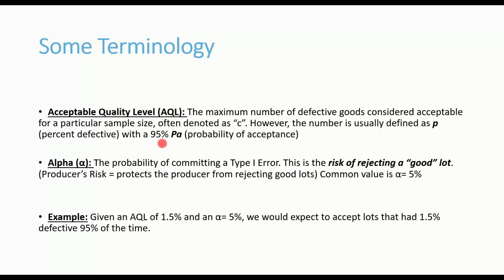In the medical device industry, common AQLs are going to be 0.4, 0.65, 1%. Okay, in pharmaceuticals, it's sometimes a little bit lower. It's 0.25%, 0.4%, and 0.65%. Those are the usual standards. But in both industries, there's often a spec AQL, and that's typically 1% defective. And lots below that spec AQL are released, and lots above it are rejected.